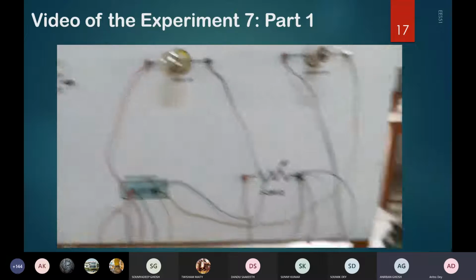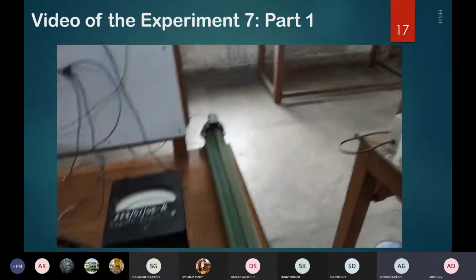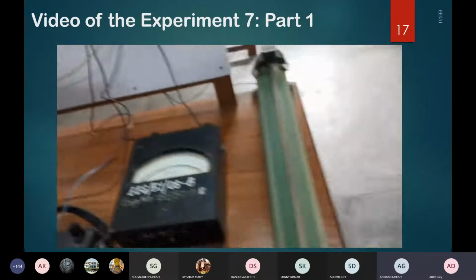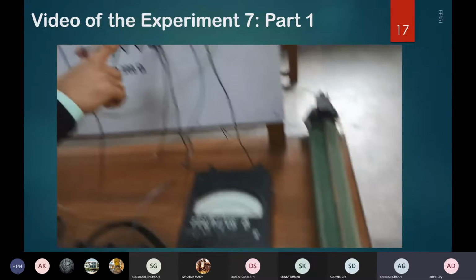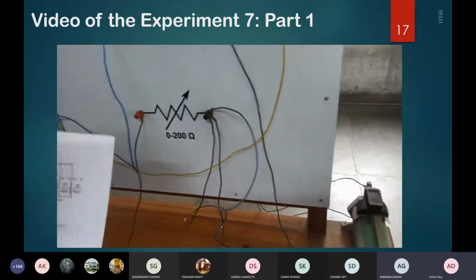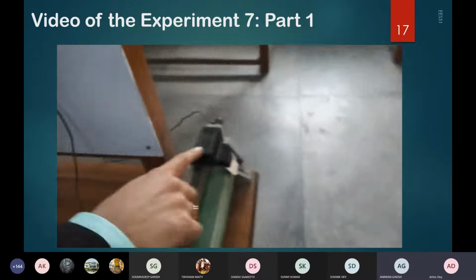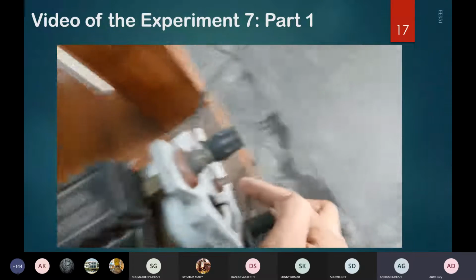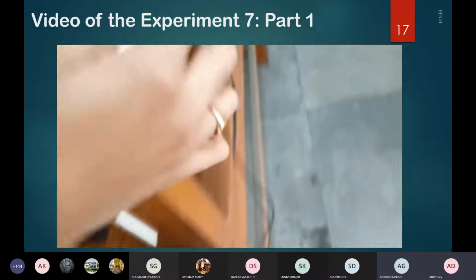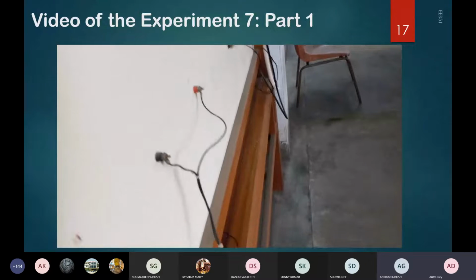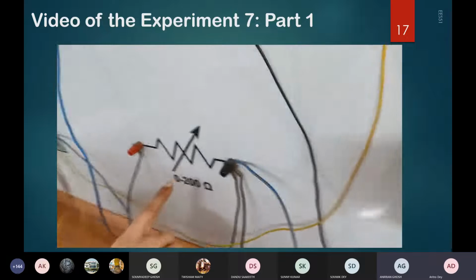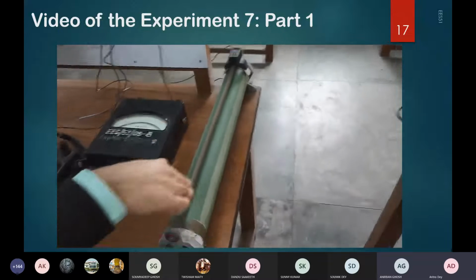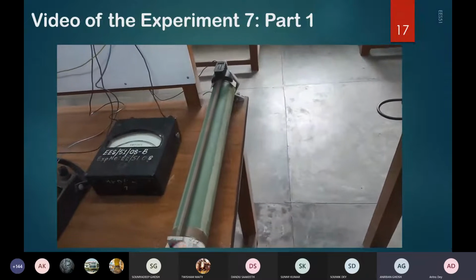So next is the rheostat. You can see from the circuit diagram, from the variac it is going towards the rheostat, which is a variable resistance. This is your rheostat, shown in the panel. It is internally connected and has two terminals. Earlier also, in the initial classes, it was shown that there are two terminals. One is here, another is there, and this is connected at the back side of this board, which you can see from the front side like this. This is the minimum position and that is the maximum position. So you can vary between these two points.